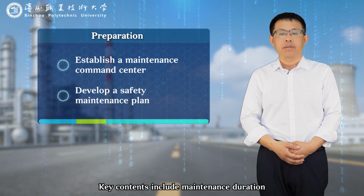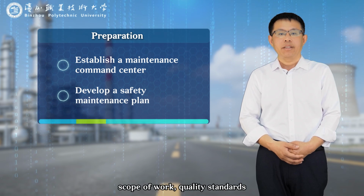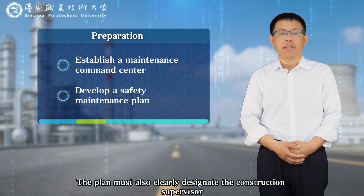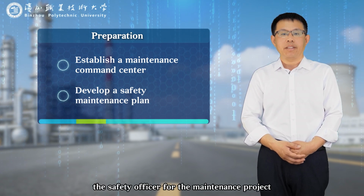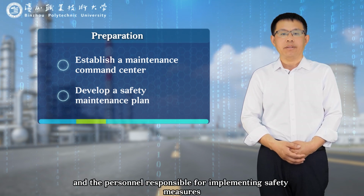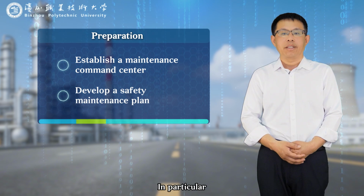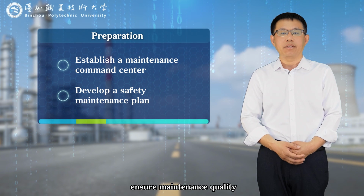Key contents include maintenance, duration, equipment, name, scope of work, quality standards, work procedures, construction methods, lifting plans, and safety and technical measures. The plan must also clearly designate the construction supervisor, the safety officer for the maintenance project, and the personnel responsible for implementing safety measures. It should further include flow diagrams for equipment, purging, flushing, and blanking. In particular, a reasonable schedule must be established to ensure maintenance quality.